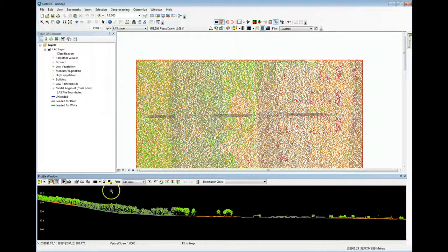And finally, I can set the depth of the profile by clicking on the Modify Profile Depth tool. It's currently set to 12.82 meters, and if I want to reduce this to, let's say, 2 meters, I simply tap in 2 meters and tab out of that dialog, or click out of that dialog. And I've now reduced the width of this profile. To dismiss the profile view, I can just click off in the X.